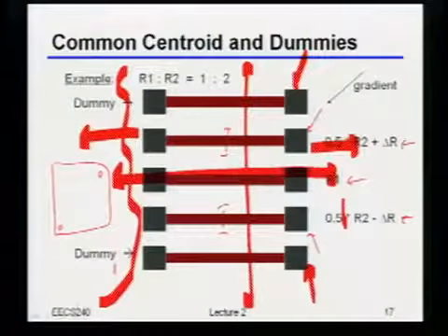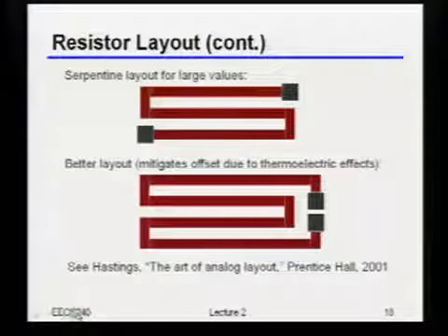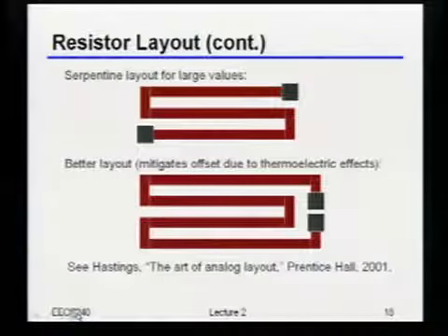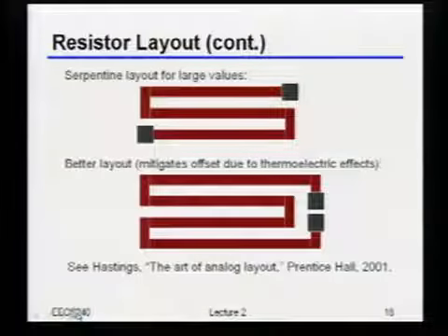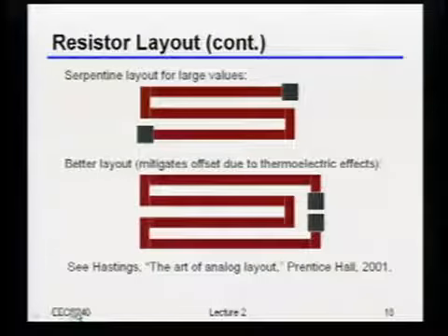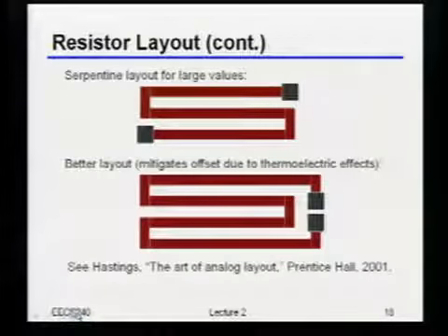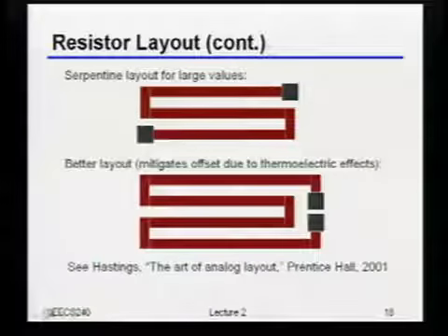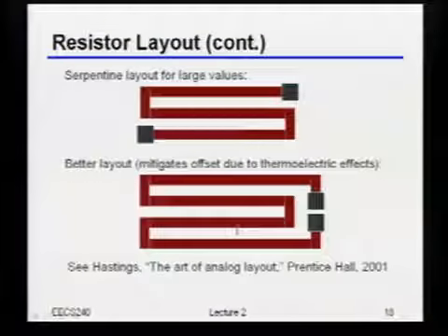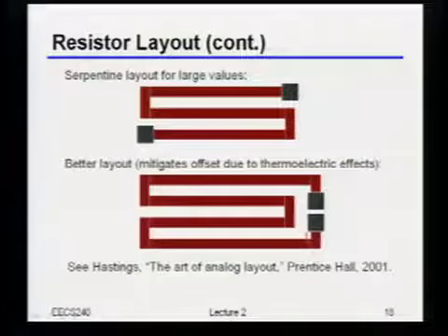Okay, good. Turns out, particularly with resistors, life can be even more fun than this, because a lot of the materials that you like to use to build your resistors out of turn out to be somewhat thermoelectric, meaning that if the temperature is different, then it actually generates a slight change in the voltage. So if you want to avoid that, there are these extra tricks you have to play, like these so-called serpentine resistors that are symmetric about one point. I'm not going to spend a lot of time talking about it.